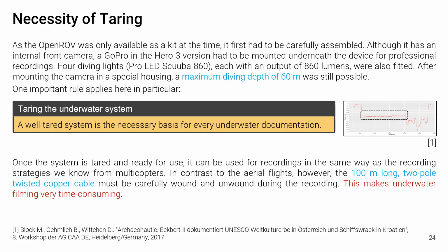However, every modification makes it necessary to re-tare the system and, for example, equip it with additional buoyancy bodies or weights. One important rule applies here in particular. A well-tared system is the necessary basis for every underwater documentation. Once the system is tared and ready for use, it can be used for recordings in the same way as the recording strategies we know from multicopters.